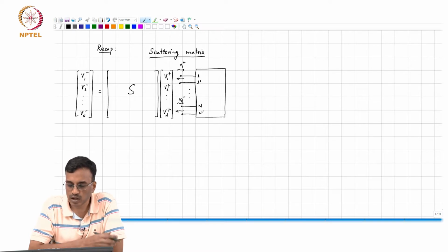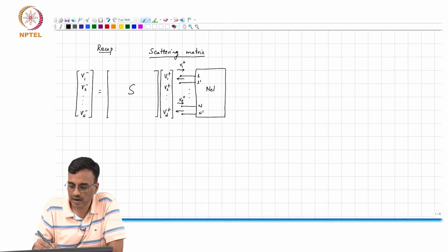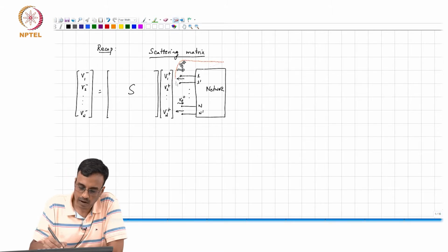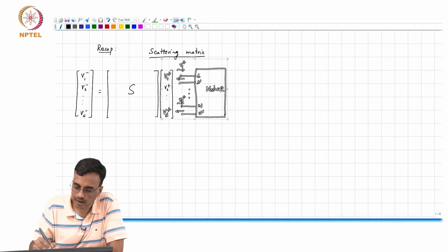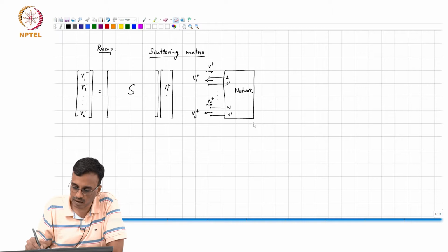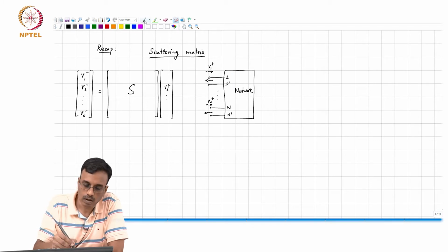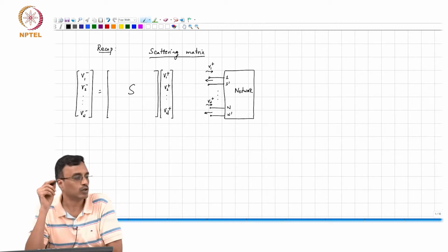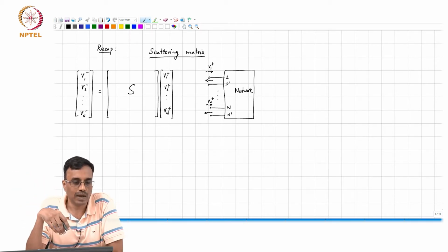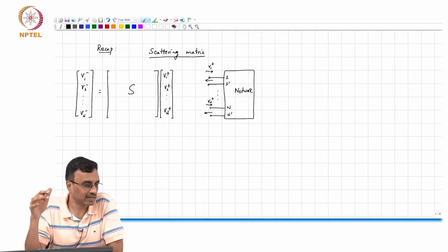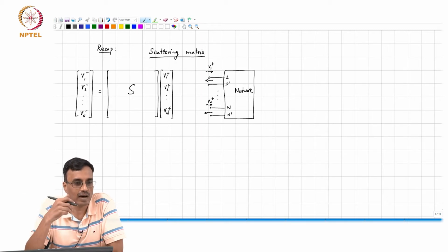And consequently you end up in a situation where, if you are trying to measure an active device, for example a transistor, the whole setup, namely the transmission line, the transistor and the entire measurement setup, starts to oscillate. That basically means that you will not be able to measure the parameters properly.